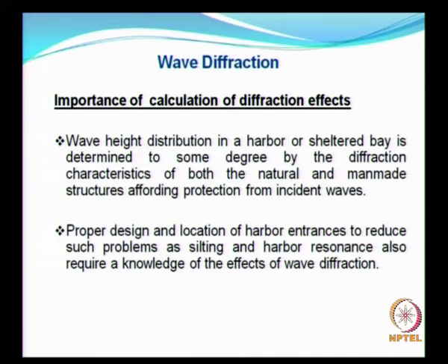problems as silting and harbor resonance also require a knowledge of wave diffraction. Particularly when a very long period wave like a tsunami enters into a harbor, what will happen? The oscillation inside the harbor will continue for a very long time, and when you have too much oscillation inside the harbor, what will happen?